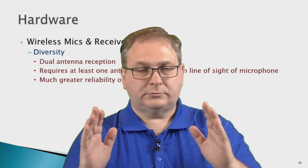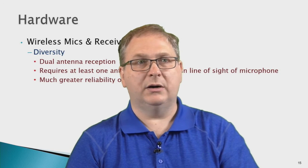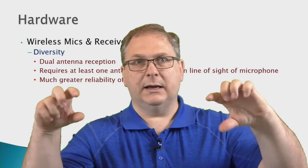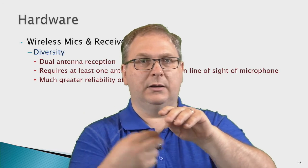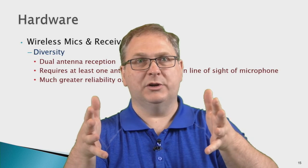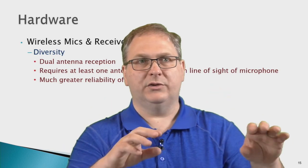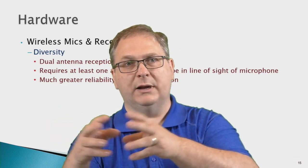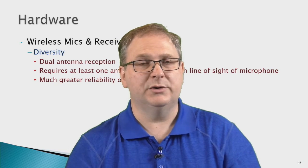And so to note, there are also different types of diversity receivers. There is what's referred to as true diversity, where you have two antennas and two tuners, and the outputs of the tuners are then combined at the receiver. And this is what gives you the best quality of reception within a diversity model. There are other types, some are called space diversity and other types of diversity. The true diversity is the one that actually is the best quality of those. And I thought I would mention that as well.